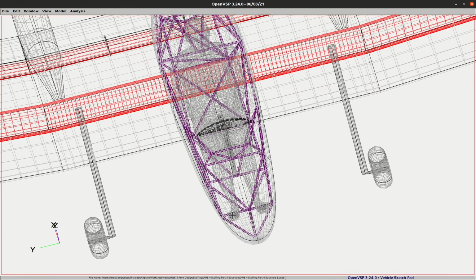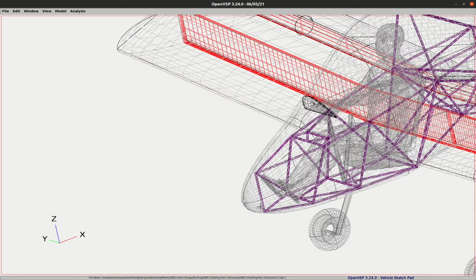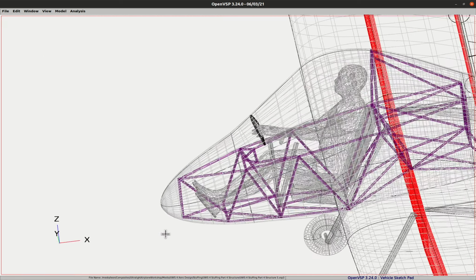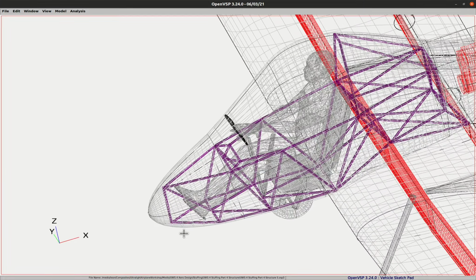There'll be a pivot point that attaches to some control pedals for the rudders. And then the load for that will attach to 2 locations on the frame, right down here in the middle and right here. Now I do have one possible issue, that any downforce isn't handled very well here. I don't have room to put something in here to handle downforce and transfer that to the rest of the fuselage. So this cross piece right down here is going to have to act a little bit like a beam to transfer up and down force over here to this beam.